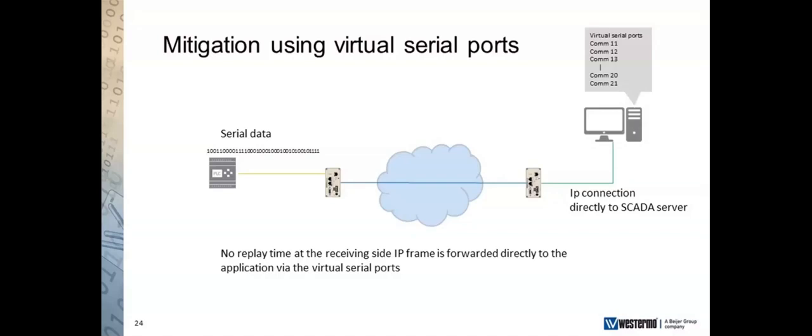There is no real limit. In terms of what you can do with some of the software which is available, you can create up to 4,000 COM ports if you really want to. It gets to a point, I guess, where it's impractical to create that many virtual comms ports because you do start using memory and resources in the SCADA system.